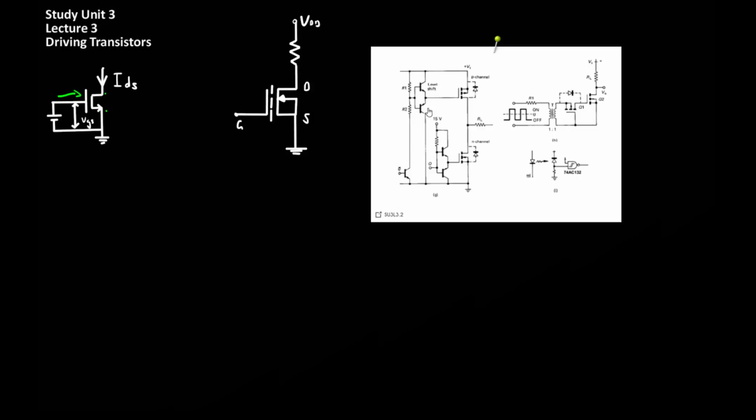The P-channel device is driven by the complement of the switching signal Q and requires a resistive bridge and a level shifted emitter follower circuit to provide the currents required for the P-channel device. The resistive bridge over here, R1 and R2, is for controlling the base voltages of these transistors, but what's important for this circuit is that the BJTs used are able to withstand the total supply voltage at this top rail Vs.